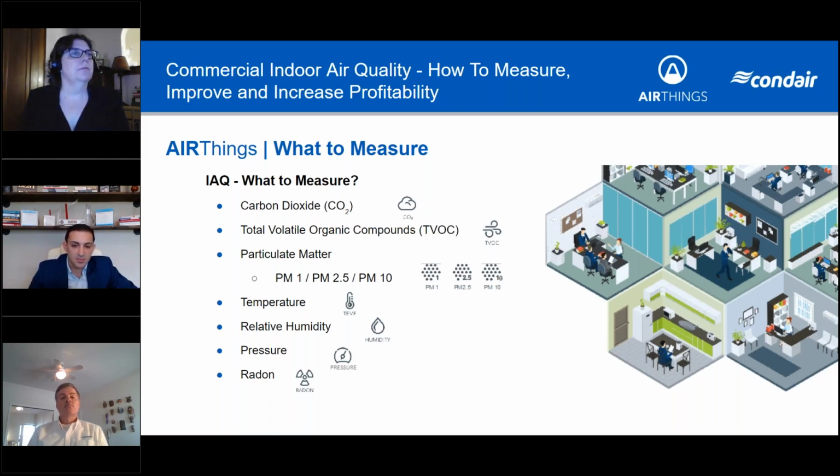One of the trends we'll cover in a little bit is how ASHRAE's recommendations have changed over the past few months, specifically to CO2 and a few other of these parameters. Another really important one is TVOCs, or total volatile organic compounds. Those are interesting because they can be anything from paints to the chemicals you're using to clean the facilities, so we really want to look at them.